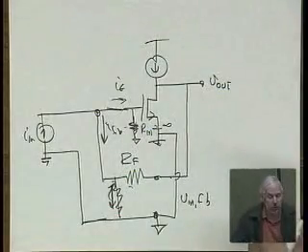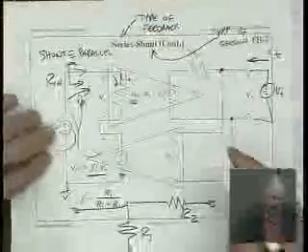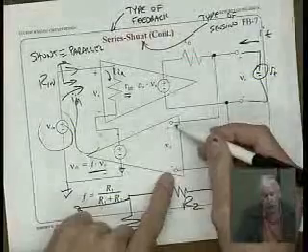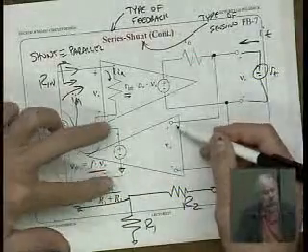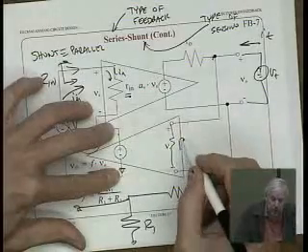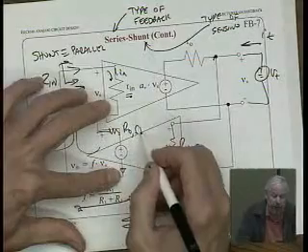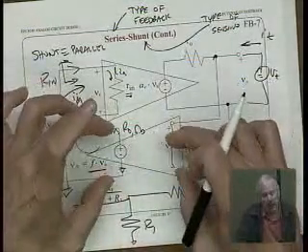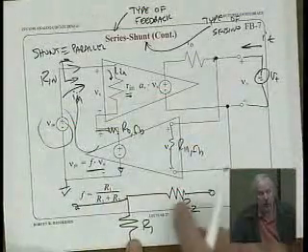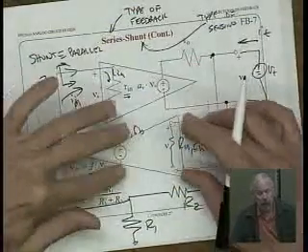What am I not including right now? Notice I have an ideal feedback network. This is open circuit voltage, and for this voltage one, I had a perfect voltage output. I have no R in of the feedback network, and I have no R out of the feedback network. I'm ignoring the resistances associated with the feedback network, and clearly they're there, right? Because here's R2 and R1.